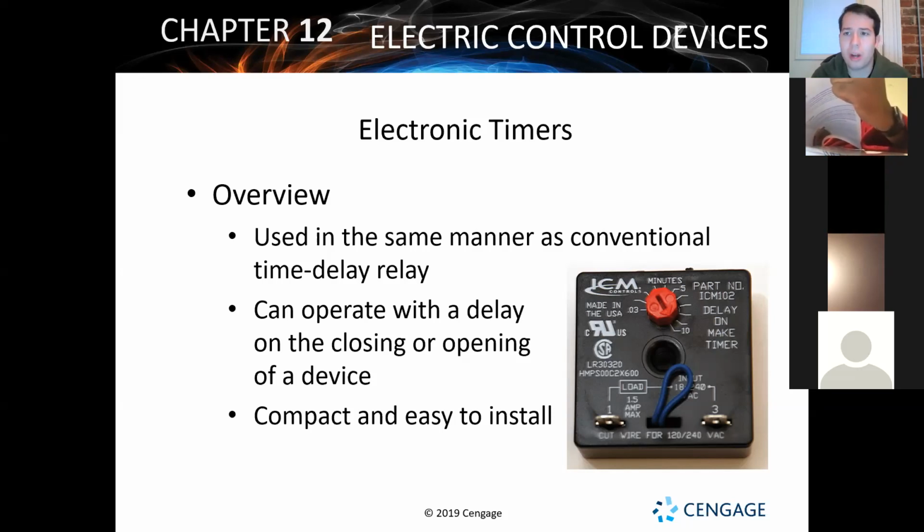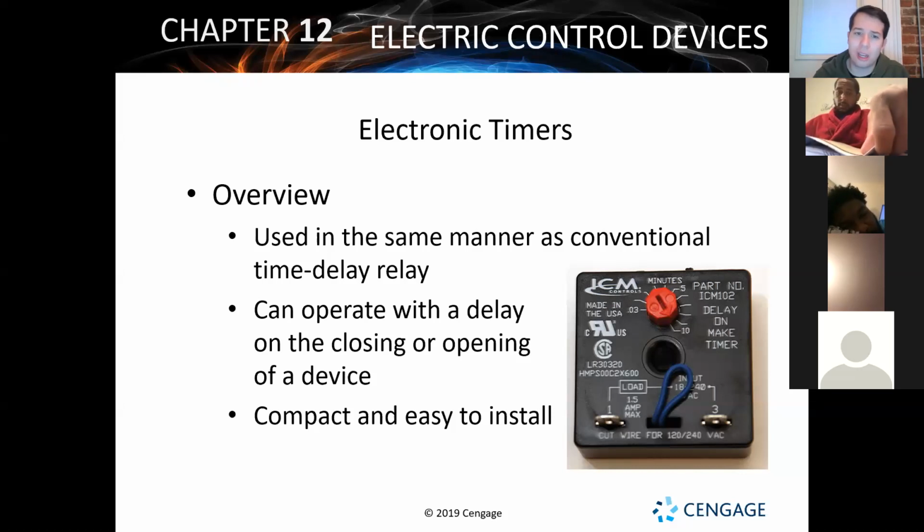So use a stopwatch on your watch or on your phone, just some way to manually count those 5 minutes. Also, if a customer comes down while you're in the basement sitting there looking at the furnace, you can at least let them know, oh, it's on a delay, I've only got 2 minutes left, as opposed to, oh, it's on a 5-minute delay, I don't know when it's going to start again. It's just more information, plus it makes your job way easier and gives you less of a headache at the end of the day.